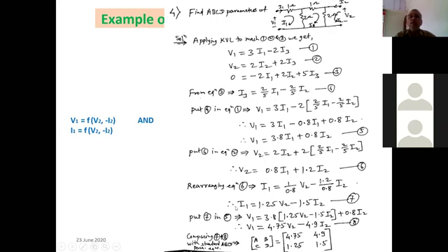Okay. And similarly, you put this equation number 7 in equation number 5 so that it results in V1 is equal to 3.8 into the value of I1 plus 0.8 I2. After simplifying this, you will get V1 is equal to 4.75 V2 minus 4.9 I2. If you compare this equation with the standard form of ABCD parameter, then you will find that the coefficient of V2 is nothing but A. So A is 4.75 and the coefficient of minus I2 is nothing but B, which is 4.9. So these ABCD parameters have got these values.